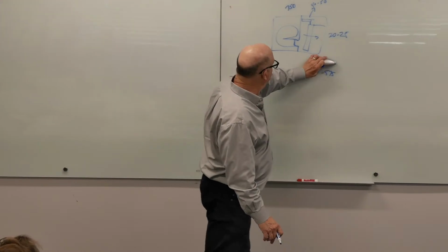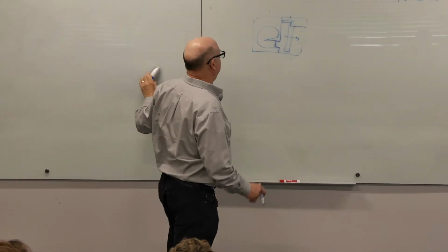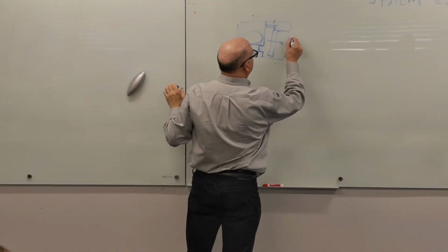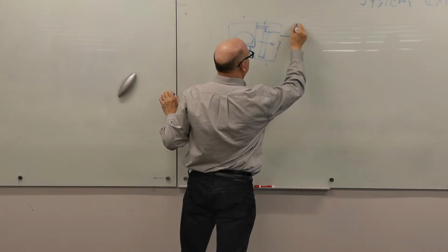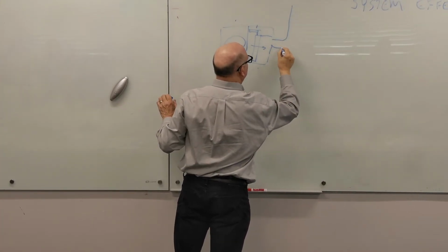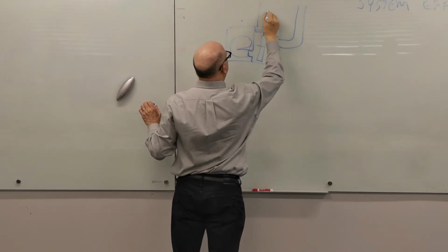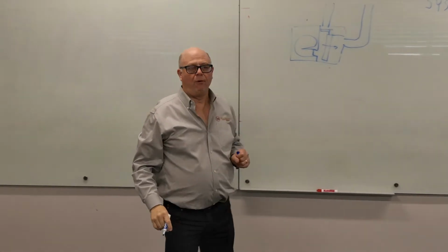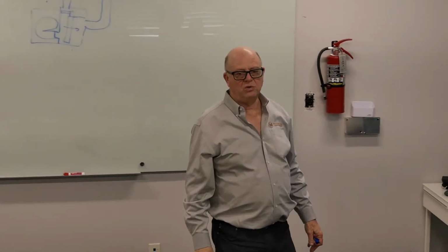And so you're going to have a big cooling coil and a much smaller heating coil, and then you're going to have the opening up here, and you will do the long radius turning vane thing to get up into the ceiling, and this one will be going straight up into the ceiling. And then you're going to run a heating and a cooling duct throughout the floor. Which one's on top?